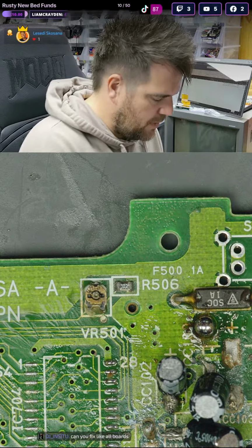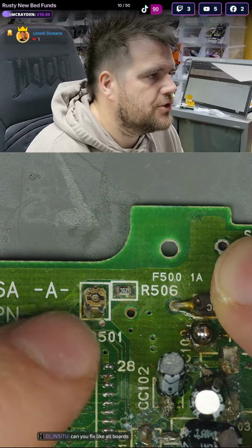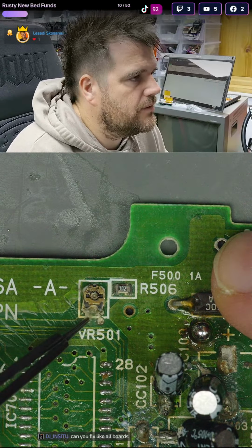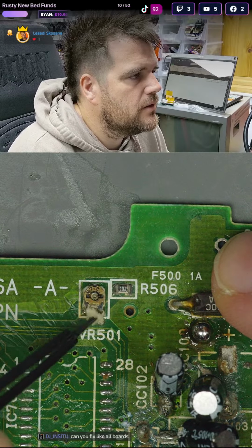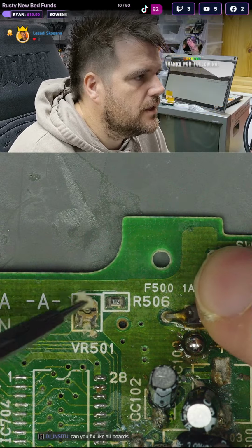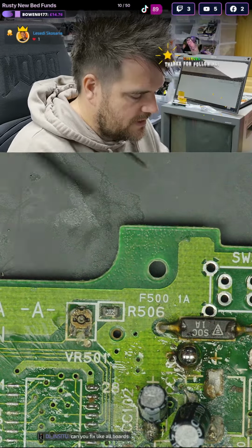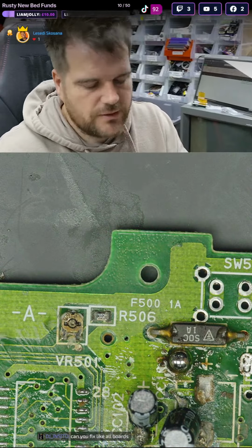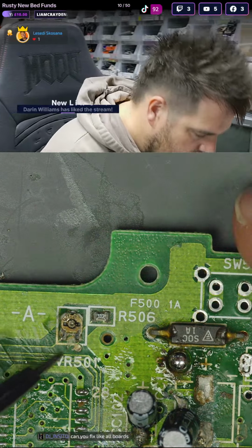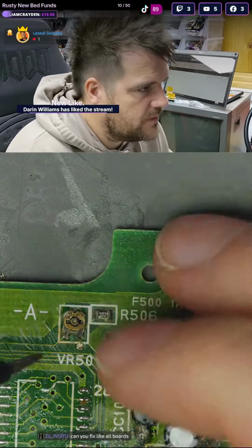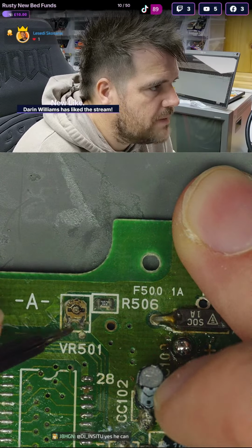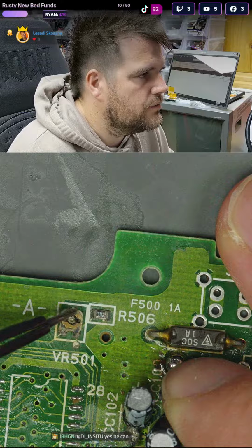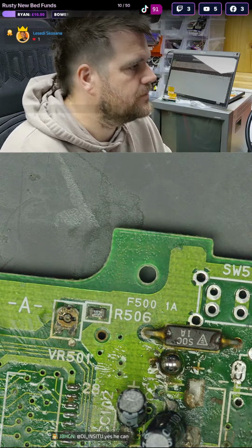Okay, let's do this pot then, this little potentiometer. This is just similar to that volume wheel that we melted the shit out of yesterday. This is basically an equivalent thing, a 3-pin. Just like the wheel, you'd have a resistance over here, a little carbon pad inside, and this arm would swipe in the middle. So it's exactly the same as that wheel that I showed you yesterday, just in a baby package. And they're always the same pinout, so you don't even need to bother with detecting pinouts or making notes. These little pots are always the same. The outer two legs are the overall, and the middle pin spins around.